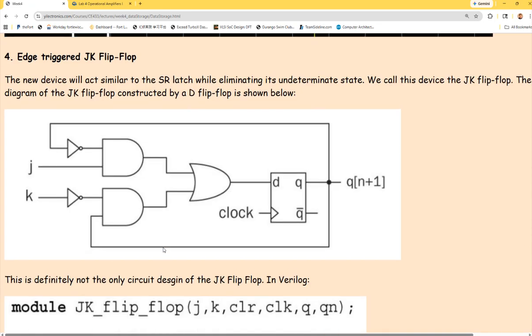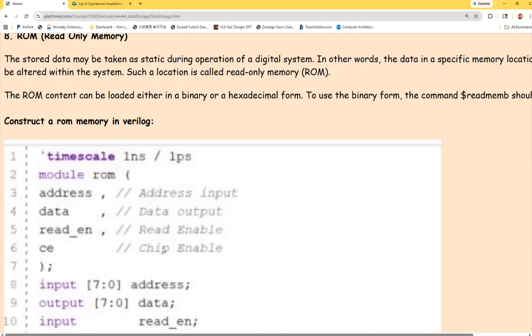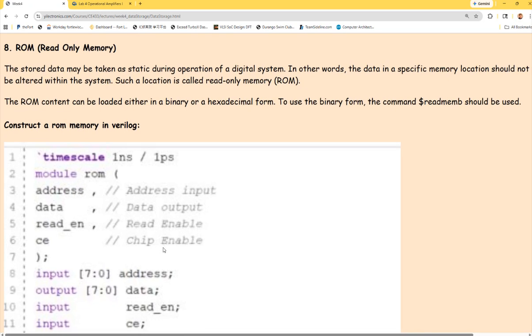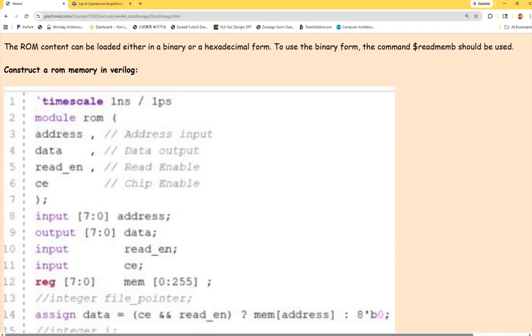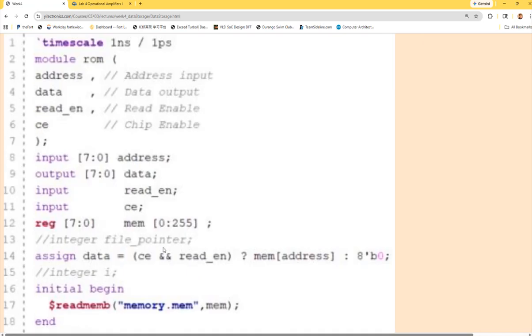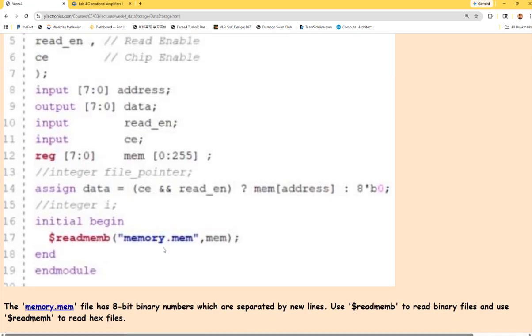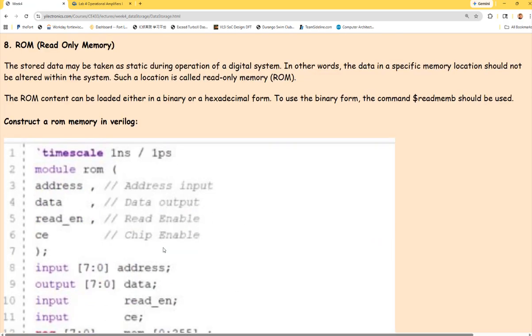So similar ones over here until a point that you see a memory file, okay? It's a ROM. So we have to cover ROM because ROM is being used for the softcore tutorial at a later time. It's exciting to see how it works, right? So you put your assembly code into a memory file, and then you compile it with the assembler.